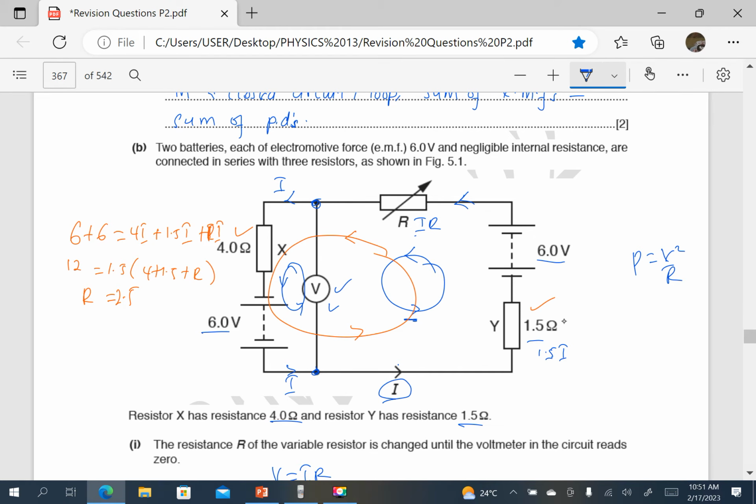It means total resistance increases. And if the total resistance increases, it means the current flowing through the batteries decreases. The power dissipated when there is internal resistance is I squared R, but remember the current is squared. We are saying if the total resistance increases, the current decreases, and the power transformed in the battery is E times I. If the current flowing decreases, it definitely means the power decreases, because power transformed in the battery is I times E.